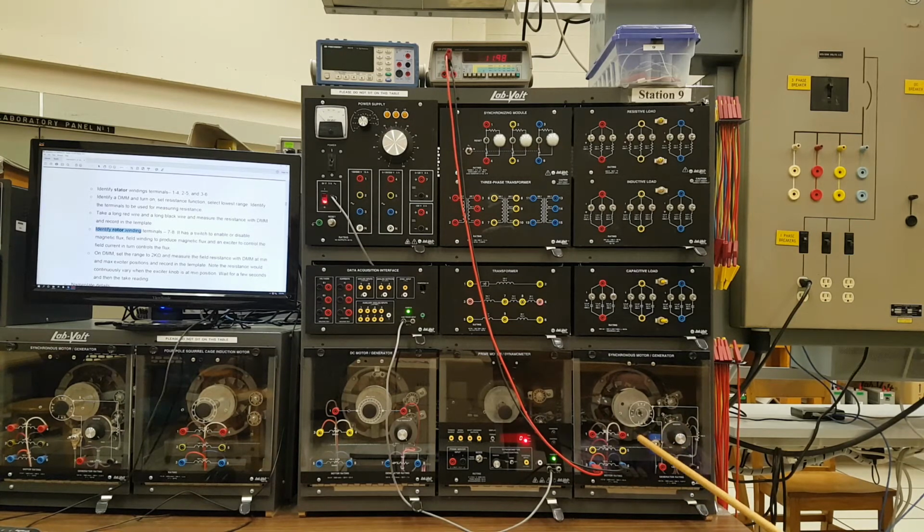If it's a three-phase system and the voltage isn't specified, we treat that voltage as the line voltage. So the phase voltage would be line voltage divided by root 3, which would be 120 volts if you calculate. As a motor it will take 0.8 amperes, but as a generator it will give 0.33 amperes.